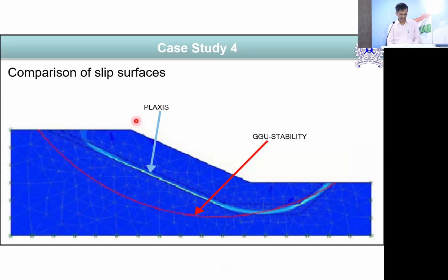Here it is different maybe because Plaxis was just trying to follow the path where there is that layer. So obviously I will try to see which is giving the reasonable result. There is a chance that this may make a reasonably vulnerable zone for sliding.